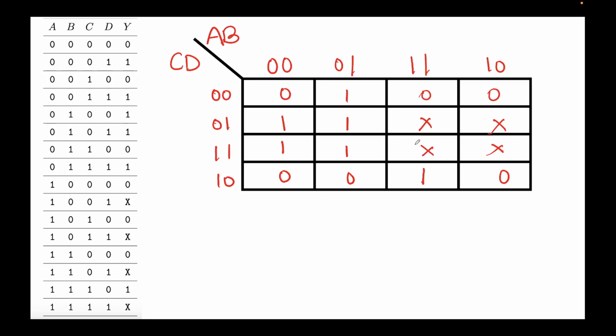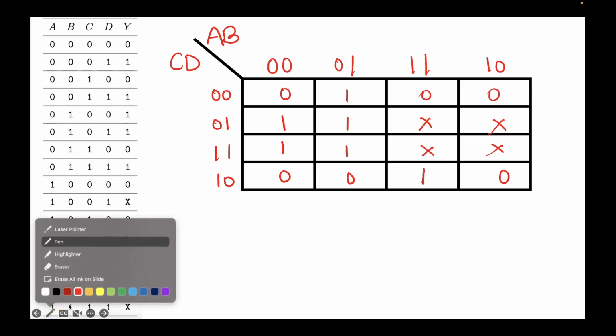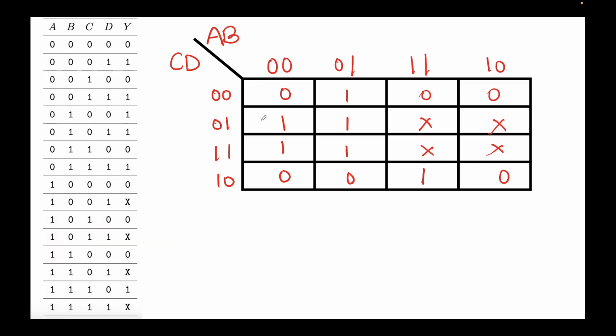Okay, so as we did the last time, we'll first evaluate the Boolean expression. First you can clearly see this here in the purple. For the purple I can write it as y1. Y1 would be, you can see, denote these rows here. C is changing, we drop that, but we take D. D is high, so we simply write D. Then we check these two columns. B is changing, we don't take B, we only take A, and A is 0, but we want 1 over here, hence we take it to be A bar.